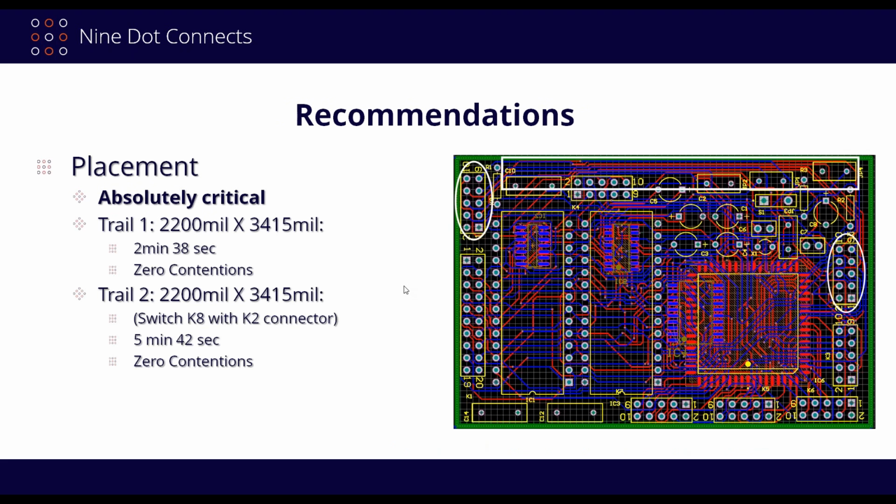Okay, so with that being said, what I want to do is give you a couple of recommendations as to how you can work the Autorouter to your advantage. First and foremost, and I don't necessarily have a slide for this, what I have found through all of the trials and errors we've made trying to get this presentation together is that if you just kick off the Autorouter and try to do a complete board, you're probably going to be a bit disappointed. More often than not, you want to use the Autorouter where it will best serve you, but that's after you've already done things that are critical to make it successful. And these are the things we're going to talk about.